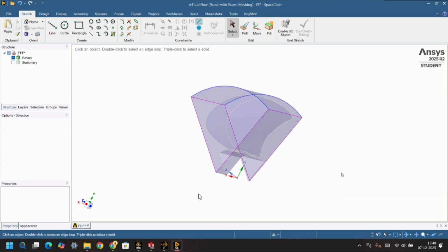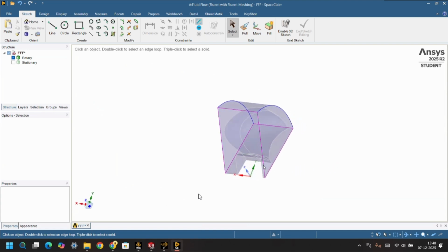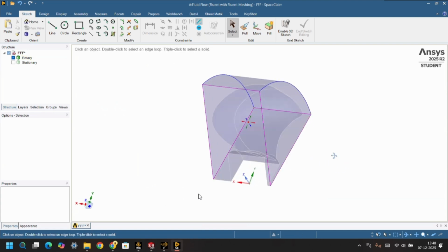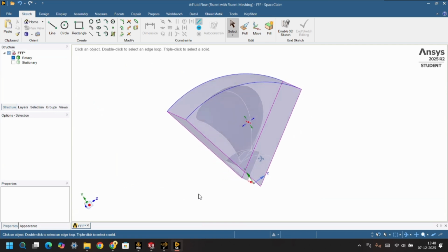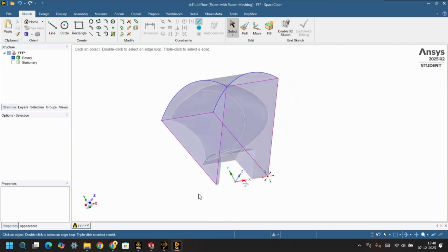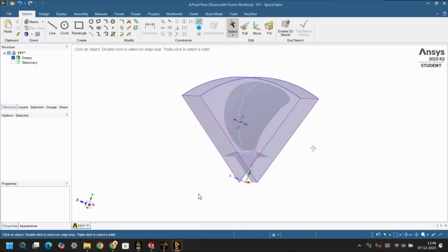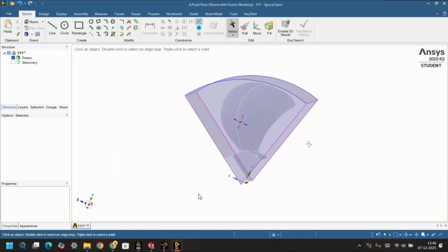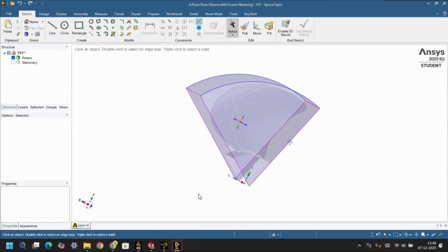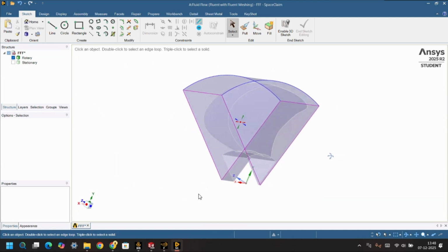In order to optimize computational efficiency and balance accuracy with the student account cell limit, we did not simulate the entire propeller. Rather, we used periodic boundary conditions by isolating 1/5 of the geometry, a single blade passage, and then imposing boundary conditions for periodicity of 5. This was a critical decision because we were conducting this in the Ansys Fluent student version, which imposes a strict hard limit of approximately 1 million cells.